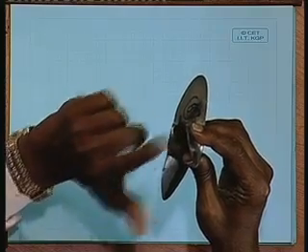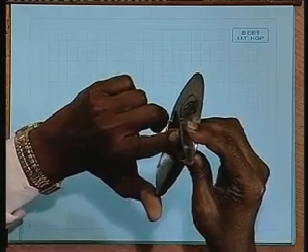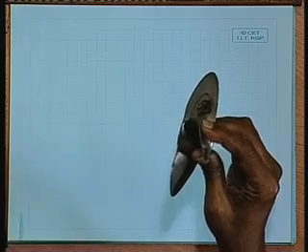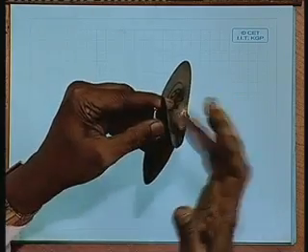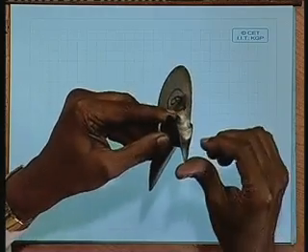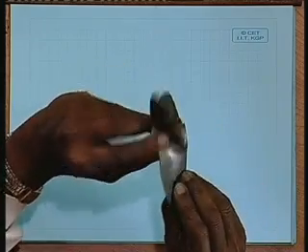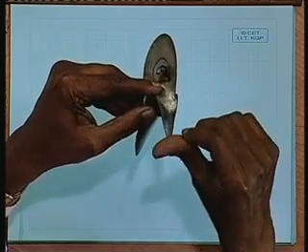But right now let us look at this right handed propeller. What are its characteristics? The side that is facing you when you are standing behind the ship and propeller, that is this side, is called the face of the propeller. This is the face, and actually it is behind on the aft side, and this is the back of the propeller, and the edge that meets the water first. If it is rotating like this, this is the edge that is meeting the water first.